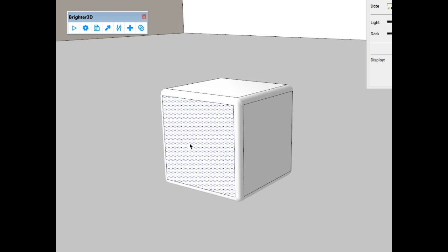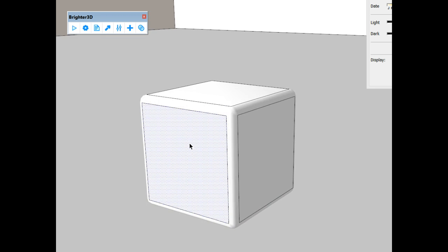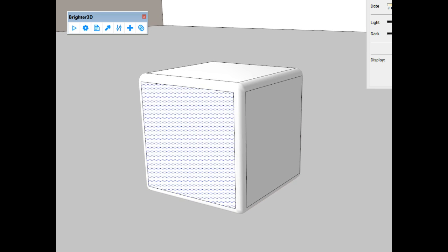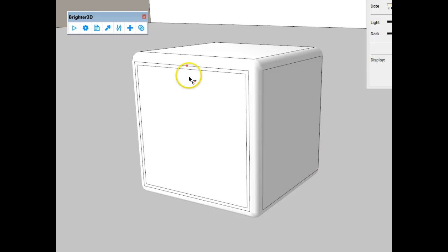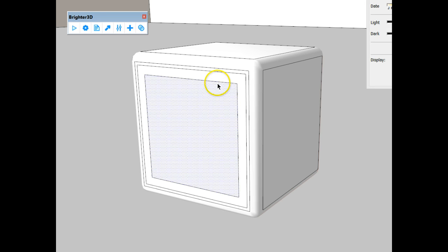I'm on this surface here, and what I'm going to do is show you little tips here. This is a new feature that's in SketchUp 2015. So what I'm going to do is I'm going to just keep away from the rounds by 1 mil and then by 3 mil. I'm going to put 3 mil corners on my labels. The reason I put that second 3 mil offset is it just saves me doing construction lines instead of drawing lines down and making a guide. You'll see what I mean in a second.